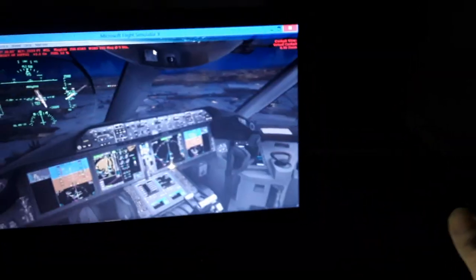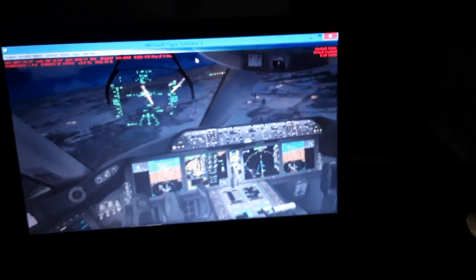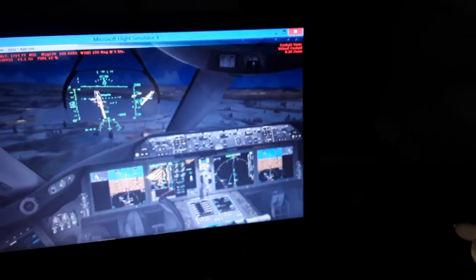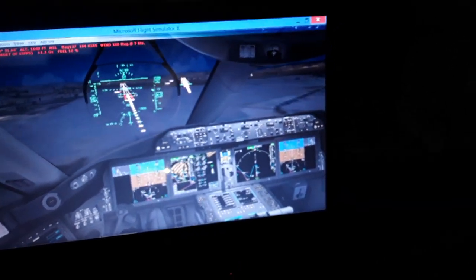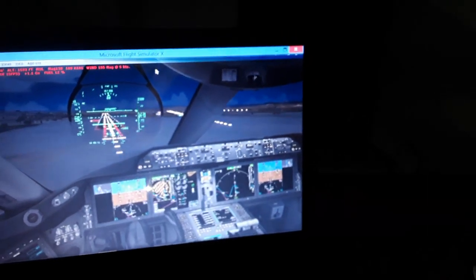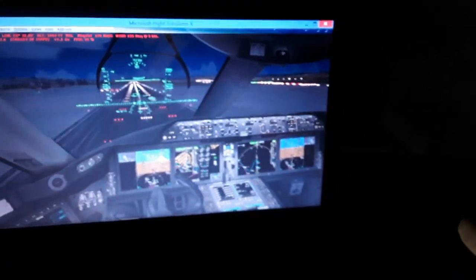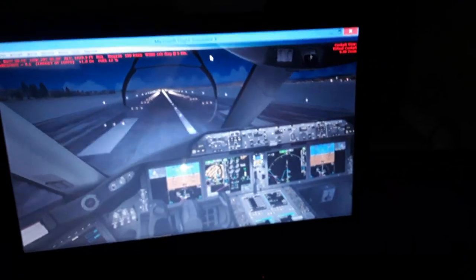So we use a little bit more airspeed when we need. Increase also the angle of descent, align with the runway heading. Also we have some side wind and some wind gusts. You can see, align with the center line. A little bit more engine power and decrease, align with the center line again over here, as you can see. So we have the flare of the aircraft, touchdown, very beautiful touchdown over here.